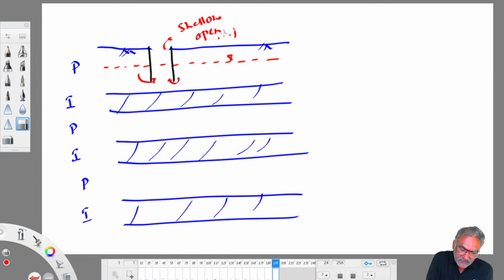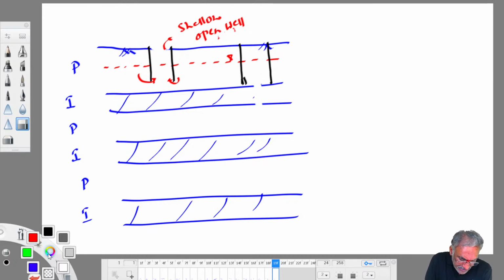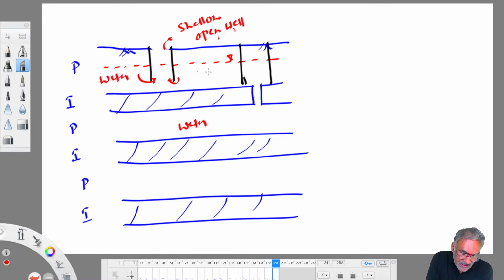Whereas a deep open well rests on impervious strata. It rests on impervious strata, and it gets water from where? The aquifer lying below it. So a small hole is made into this impervious strata. It doesn't collect water from this top aquifer. It collects water from the aquifer lying below the impervious strata. A small hole is there. So water from here, here also water is there. This water is collected, rushes into this well and finally accumulates there.